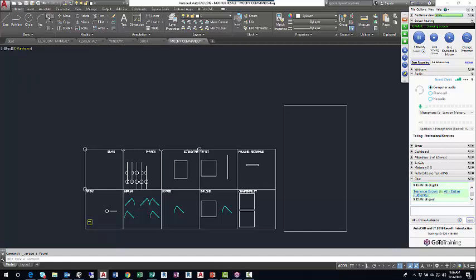Well, Rectangle and Polygon, their workflow is not similar, but they do create already closed polylines, right? So I'll go Polygon, the command prompt, once I, again, habitually moving my crosshairs into the drawing window, enter number of sides. 4. I want 8. 8, not 58, 8. There we go, 8. Enter.